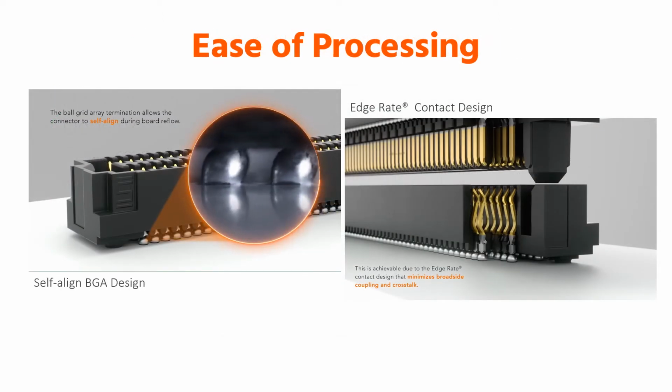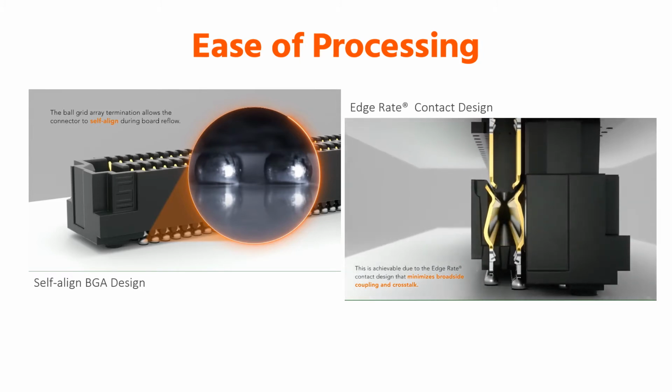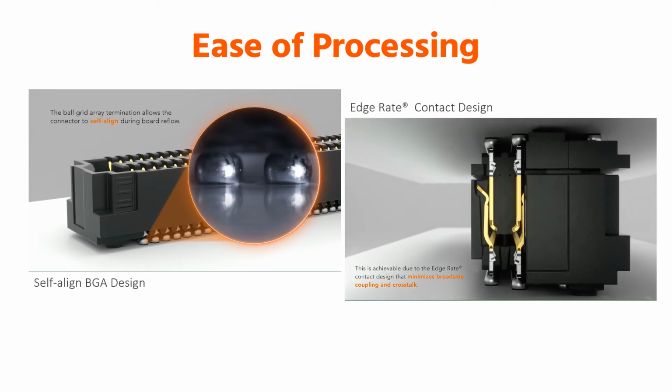The connector is soldered by BGA balls, which means there's a micro justification, which is important for extremely accurate positioning of the connector, so that the fitting between module and carrier is quite easy. And it got an enhanced contact system with quite long contacts, which means even with some movements, some shock and vibrations, a reliable contact is guaranteed.